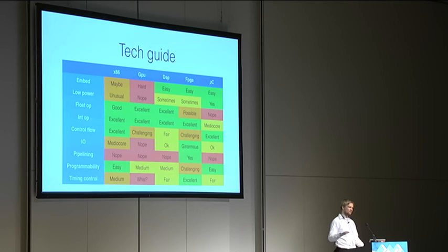Control flow is quite hard to do. You have to create state machines, those ones that you heard about in your lectures during university and thought, wow, why would I ever need that? For programming FPGAs, you need those. But the I/O capabilities are ginormous. There's a 1,000 pin FPGA that you can buy, and you have multiple hundreds, like 600 or 700 general purpose I/Os that you can use for whatever you want.